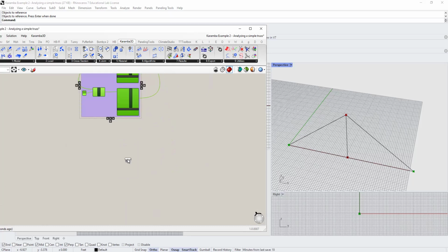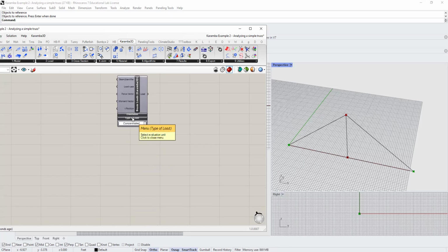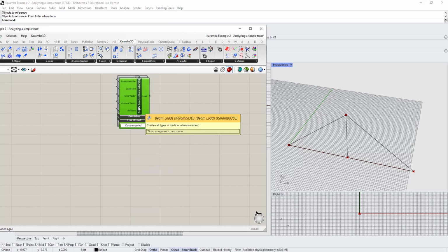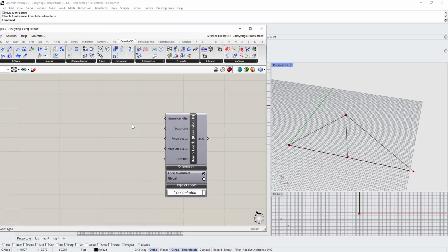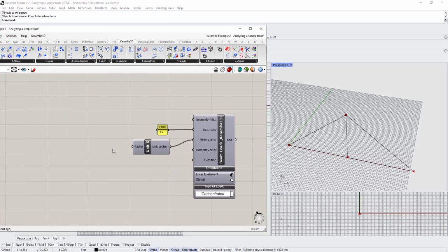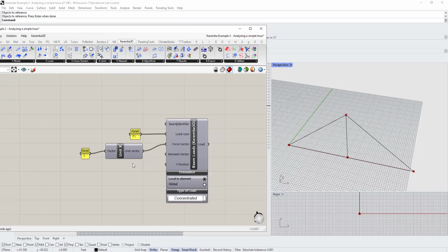So I'm going to pick loads, and we're going to have 2 point loads. And both of them are concentrated loads. I'm going to give it a name like F1 and define the vector. So first I'm going to define the horizontal vector. And the horizontal vector was positive 2 kilopounds, which means that the 2 kilopounds is along the X direction. So I'm going to call unit X to define the direction and drop a panel and give a magnitude of 2 to that vector.